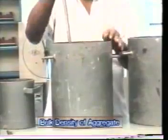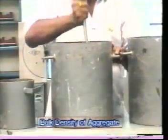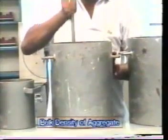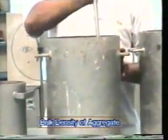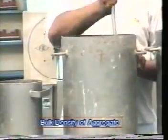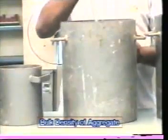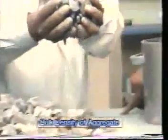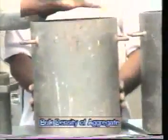Now the measure shall be filled with the material in about 3 different layers, each being tamped with the tamping rod 25 times. Here this tamping is for the best possible natural orientation of aggregate particles, not for compaction.